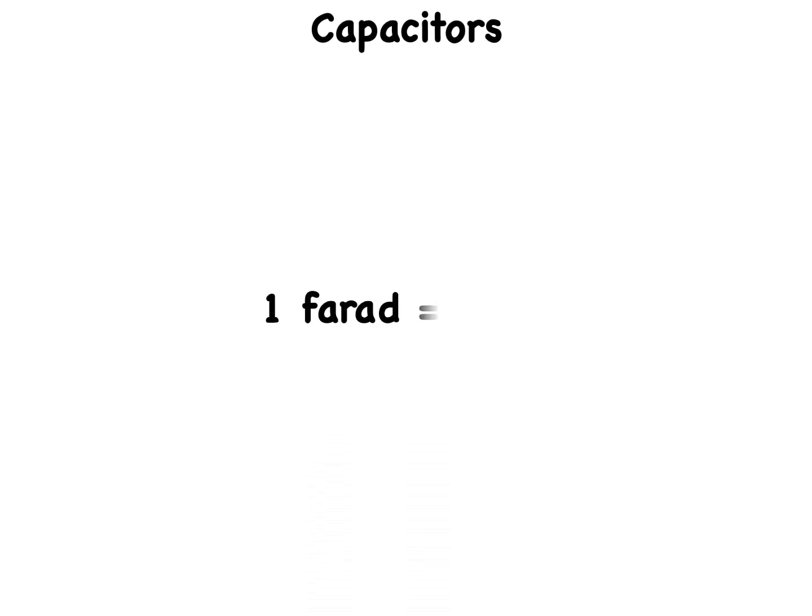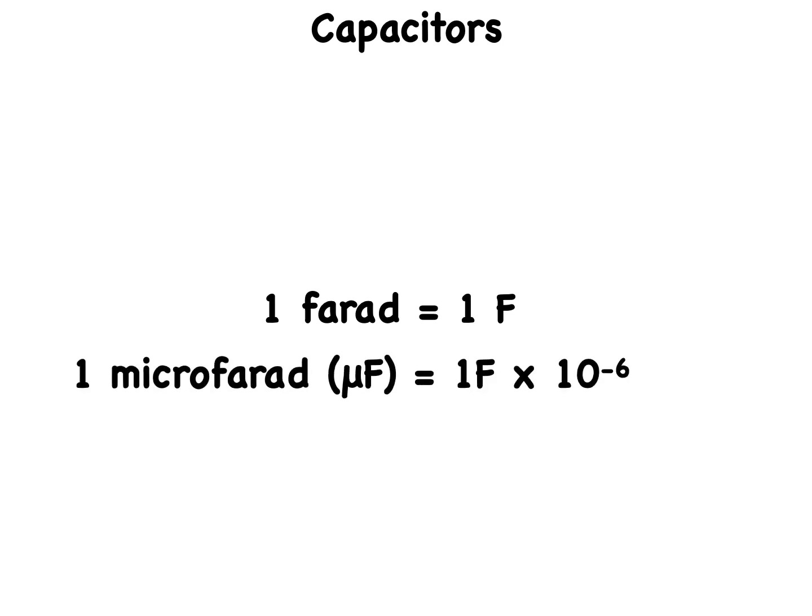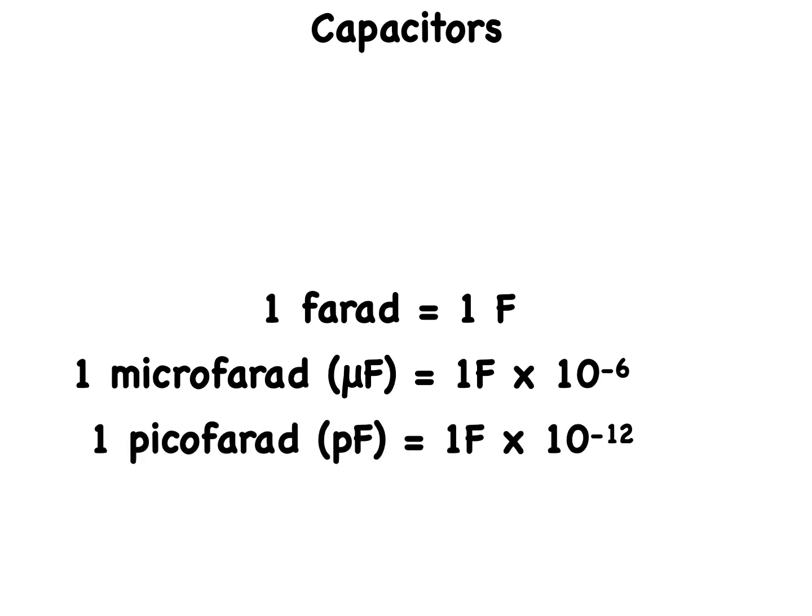The farad is a huge electrical quantity, and most real-world components are therefore rated in tiny fractions of a farad, microfarads or picofarads. A microfarad, symbolized μF, equals 1/1,000,000 of a farad, and a picofarad, symbolized lowercase pF, equals 1/1,000,000 of a microfarad or 1/1,000,000,000,000 of a farad.